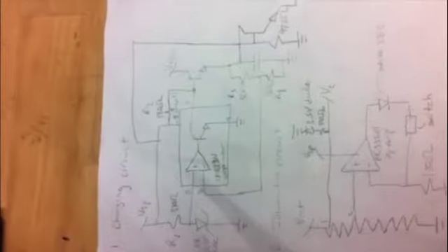This is our charging circuit. The purpose of the charging circuit is to be able to charge a 1.5 farad 5-volt capacitor up to 5 volts from the solar panel rail, whose voltage is supplied by the 9-volt solar panel. This charging circuit is important for the rest of our circuit, as it is responsible for powering all the rest of the circuits in our system.